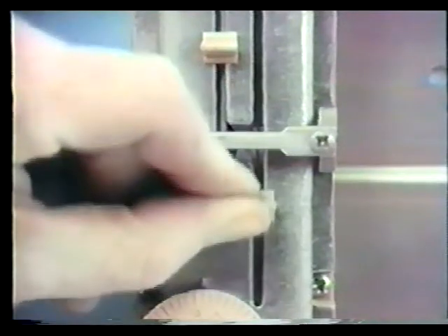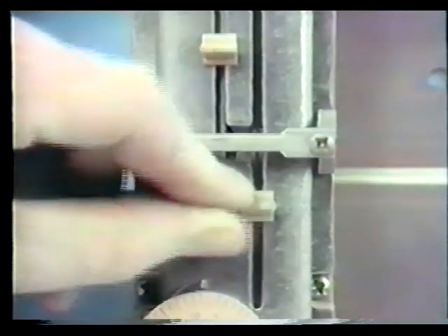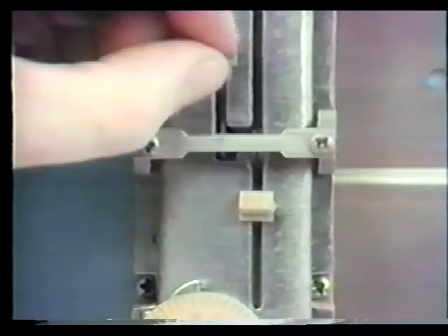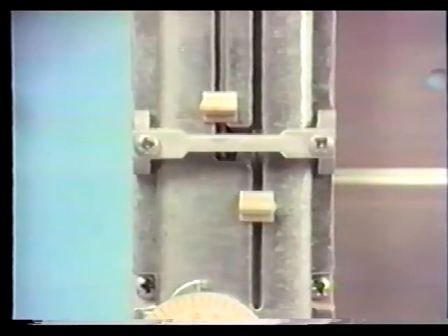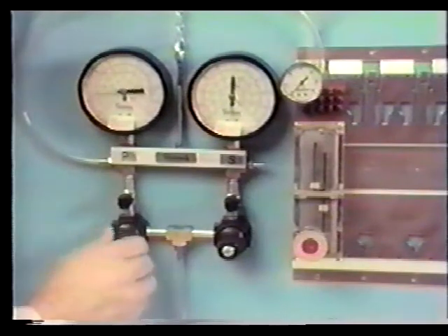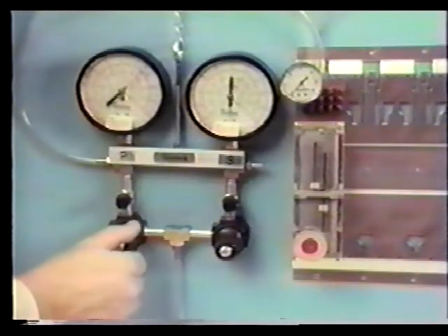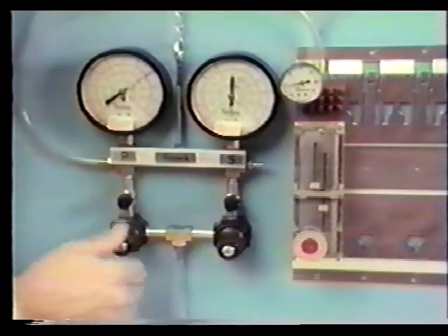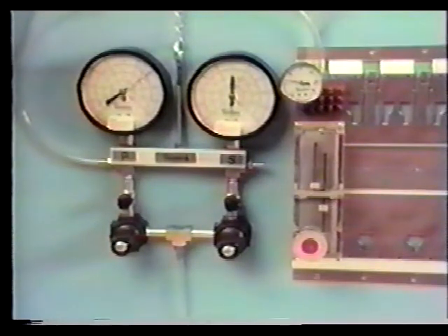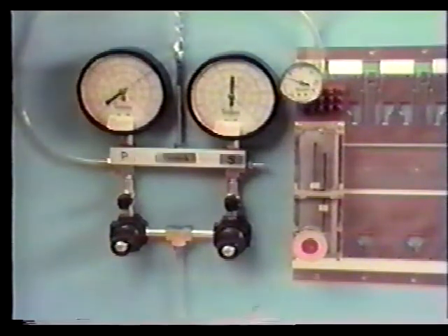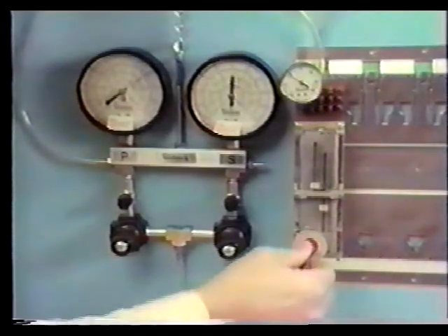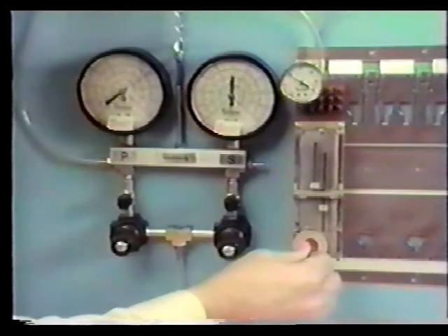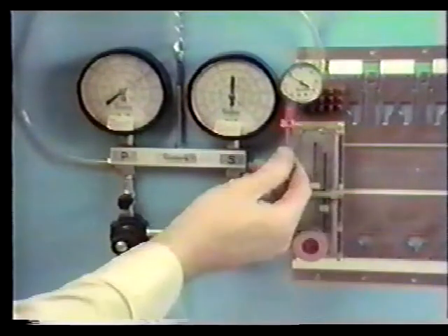So, move the throttling range slide to the 10% mark. Set the authority slide to 10% or the minimum setting. Set the input pressure or reference temperature on the primary input receiver gauge to a value within the range of the transmitter to be used. Adjust the control point adjustment to match the temperature reading by adjusting the branch output pressure to 9 psig, or the midpoint of the spring range with the calibration tool.